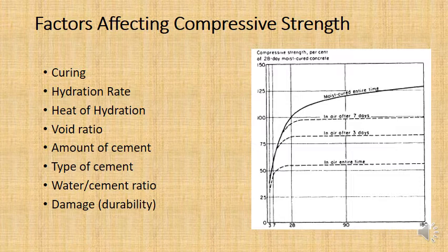Now, equally, the hydration rate has an effect on the compressive strength. There are some cements that react very quickly with water and others which take a long time. That's important because if it reacts very slowly, potentially the water will evaporate in that time, especially if you haven't cured it correctly.